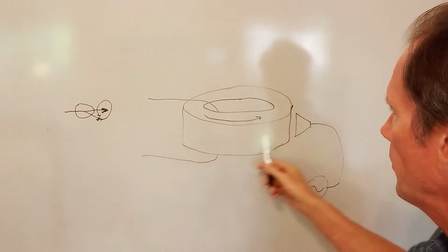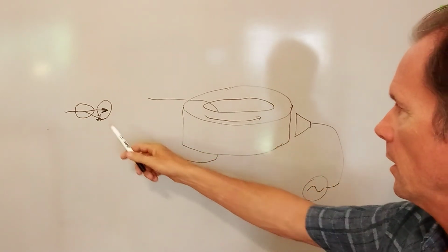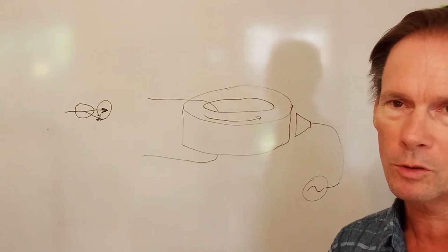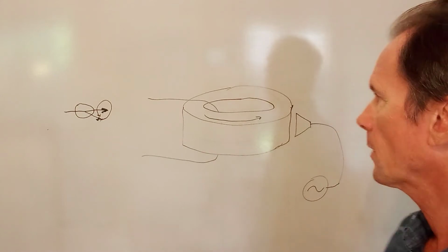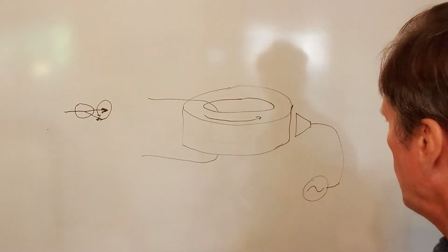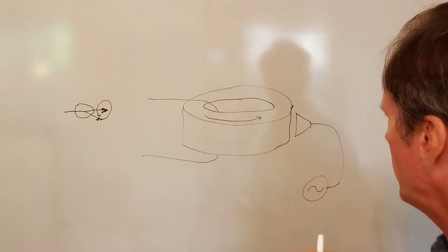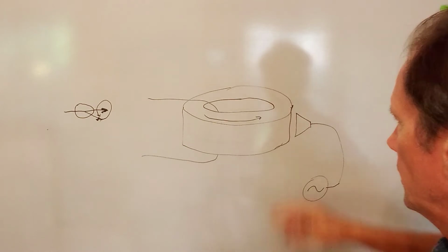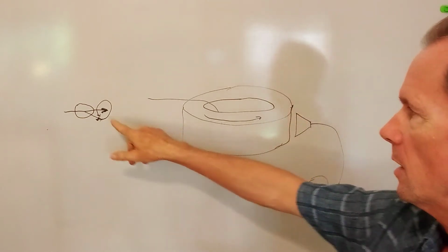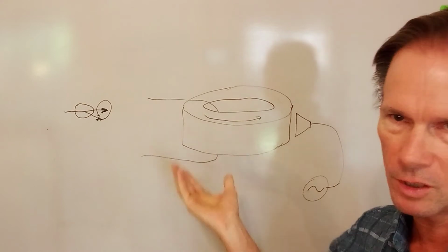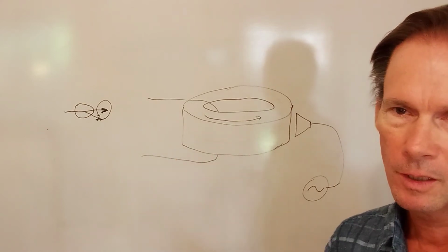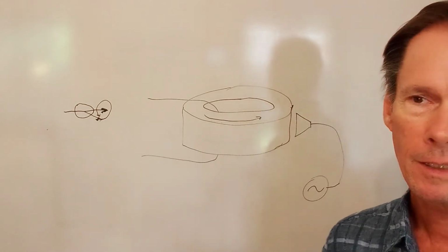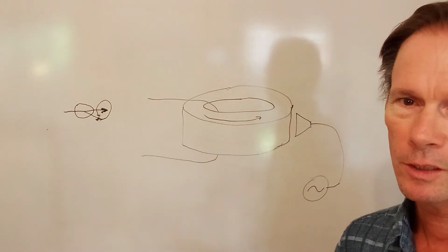The stronger the real magnetic field is, the higher the frequency these tend to wobble or gyrate or precess. So if you have a generator and you're generating around microwave frequencies and you sweep past the frequency that these things want to wobble at, then you'll see an increase in how much the material will absorb, or in some cases reflect, the magnetic field at those frequencies.